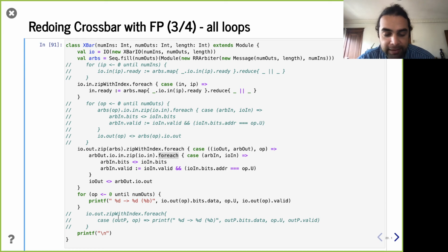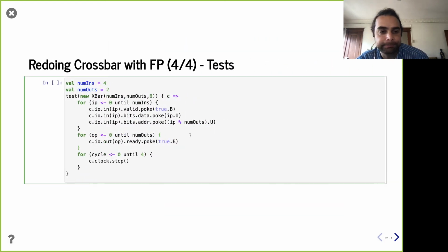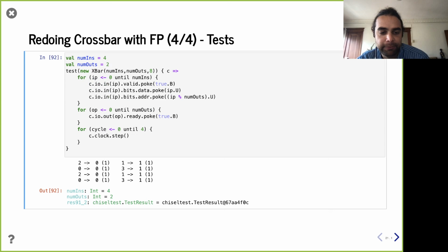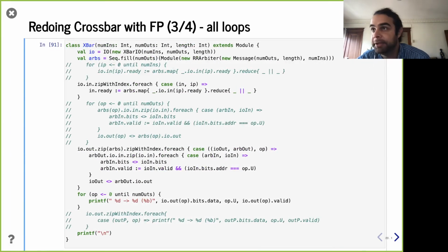And although we can't see it, I think this is going to run without issue. Go ahead to the next slide and run this over a test bench. This is a test bench from before. So, we're trying to send from 2 to 0 or from 1 to 1. You can see it's alternating because we're using a round robin arbiter, but the key point is it works, right? Cool. So maybe I'll go back here while we take any questions or comments, discussion points, etc.